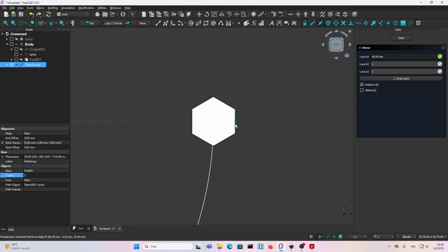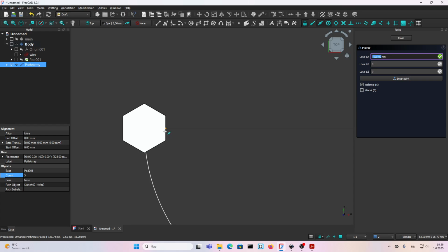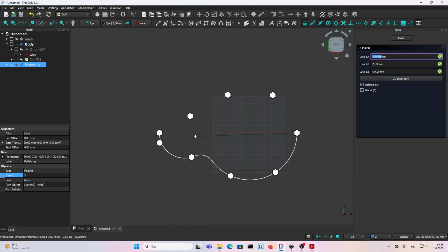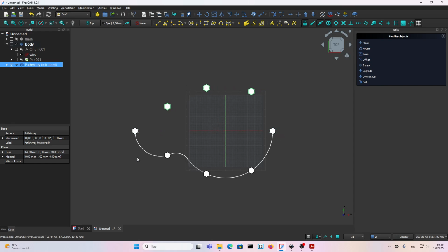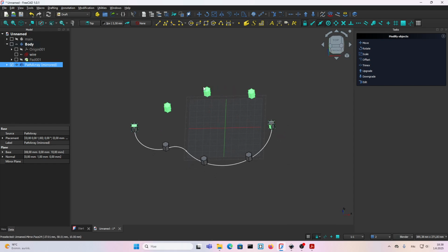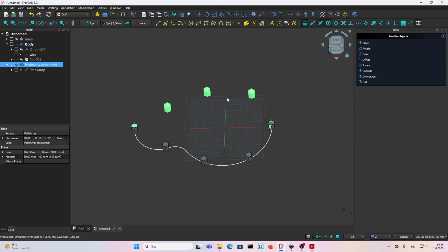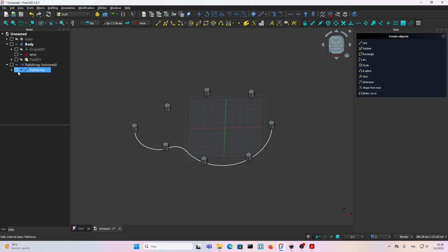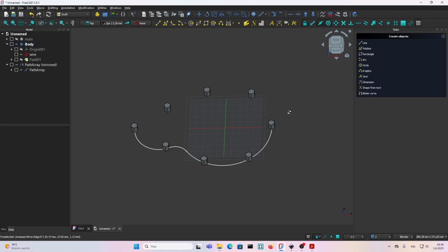See, this is the midpoint. Click on here, and you can snap onto the other midpoint like this, or you can hold shift from the keyboard and it's going to be straight like this. Click. Now we have our hexagons in here. One notice, if you take a look, if I choose this one, I have 5 hexagons. If I choose this one, I also have 5 hexagons. So in here we have two on top of each other. Just keep this in mind.